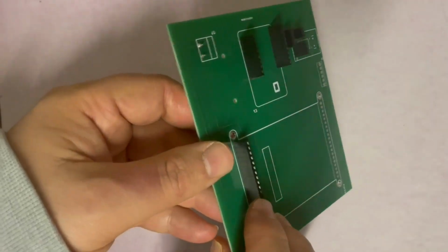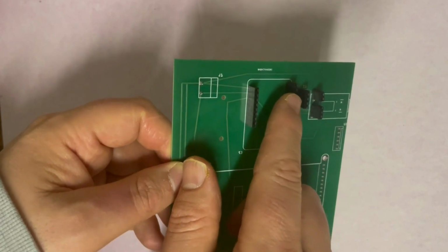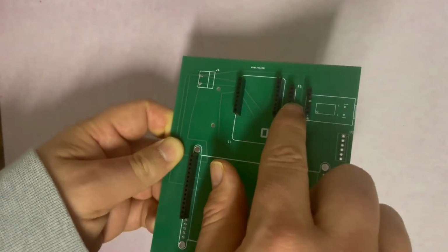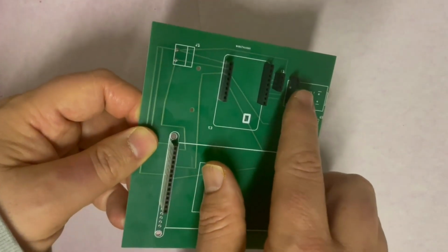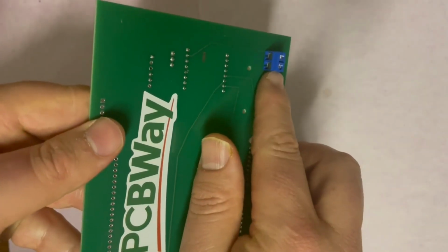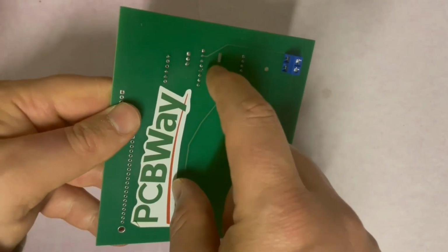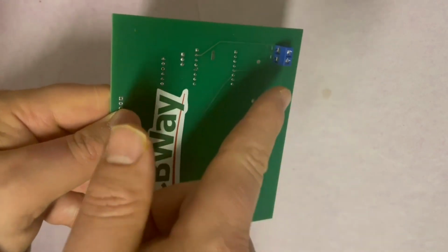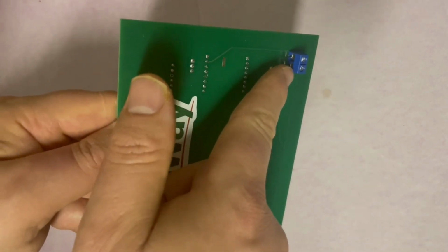So I've soldered on the header pins now, so I can just plug the TFT and the ESP32 in. And this here is for flashing it. This connects the 0 pin to ground, and this is for the FTDI. And on the back, I've soldered on the terminal screws, because I'm going to mount the battery on the back of the PCB. It's just going to make it a lot easier to have the terminal screws on the back here.